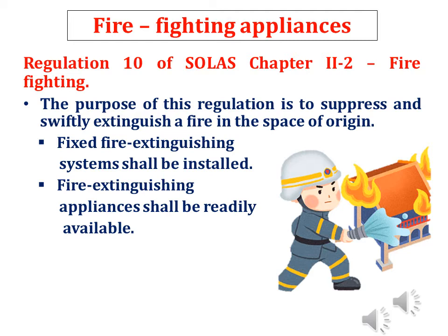Fire-fighting appliances. Regulation 10 of SOLAS Chapter 2.2, Firefighting. The purpose of this regulation is to suppress and swiftly extinguish a fire in the space of origin. Fixed fire extinguishing systems shall be installed. Fire extinguishing appliances shall be readily available.